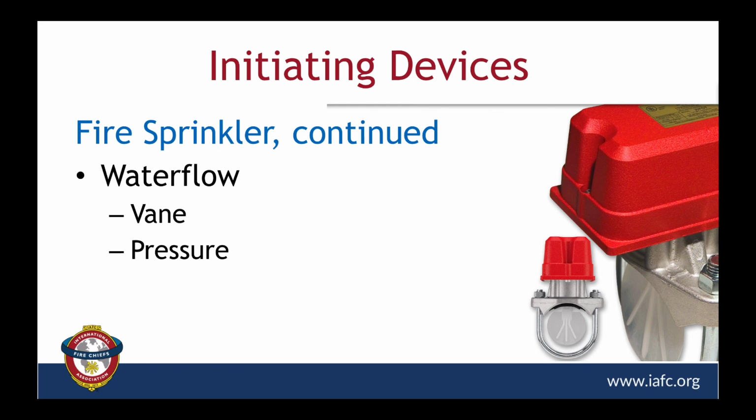Whereas pressure switches detect water flow from changes in the water pressure. Now, these devices serve largely the same purpose as water flow switches in wet type systems, and they will sound an alarm when the sprinkler head or the sprinkler heads have been opened.